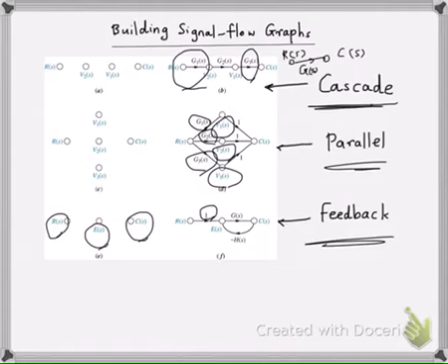So that is becoming an input to this E here. So really E is going to be R minus HC. And then this E is going to serve as the input to your G. So really your C is just going to be G multiplied by E.